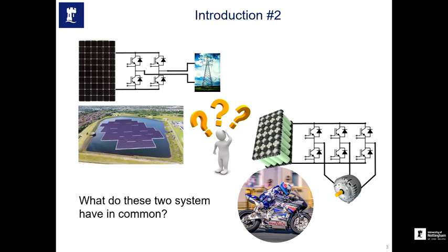And the second application, as I mentioned, is this three-phase inverter. As you can see, in this case we have 1, 2, 3 half bridges. To create a three-phase inverter, you basically connect 3 half bridges in parallel. And then by using modulation techniques, you can convert the DC voltage, which comes from this battery stack, or battery pack, to the AC voltage needed for the motor.